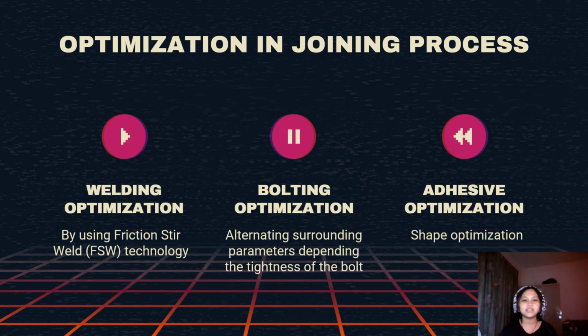Next is the optimization of the bolting process. Changing the rotation speed of the bolt, the size of the bolt, and the temperature of the surroundings are some of the important factors of bolting optimization. The clamp length, also known as the free length of a bolt stretched under tension, should be at least 3 to 5 times the bolt diameter. Increasing the elasticity of the fastener also helps in optimizing the bolting process as it can help reduce the settlement effect, where it increases the elongation of the bolt, reduces the risk of self-loosening, and minimizes load transfer loss.